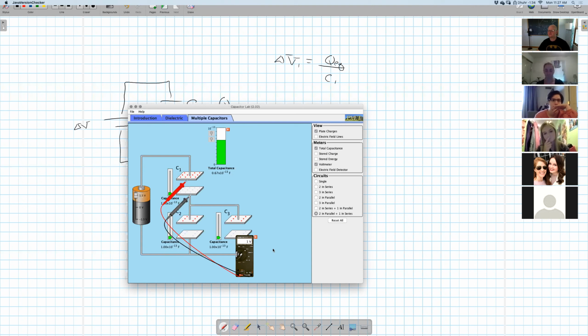That's right. And the total capacitance you'll just get from here. Sometimes you might have to zoom in or zoom out, and you're going to guesstimate what it is off of here. Actually, no, it does say down here. So this says that the total capacitance is 0.67 times 10 to the minus 13 in this particular case.